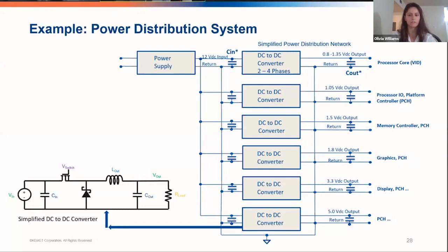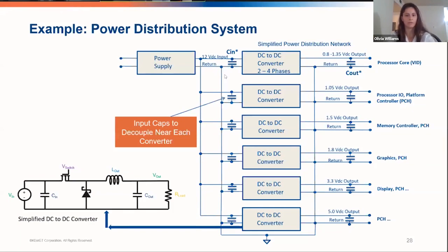much. So we can see here all this coming off of the same power supply. We want to get the decoupling capacitors as close as we can to the input rails there, and then also on the output. So ultimately, what matters is that the active device should be connected to an impedance low enough that the current transient generated will be within our noise voltage limits.